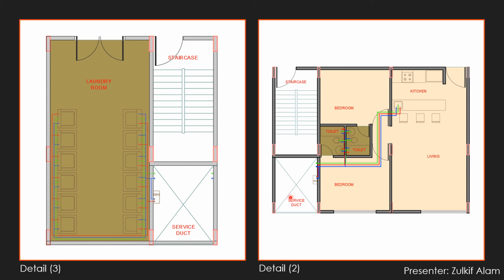Each floor receives a water line through the service duct, which branches off to a water heater specific to each apartment. This water heater provides the hot water system for the apartment. The green line in this diagram depicts the wastewater system, and the red and blue lines depict the hot water and the cold water lines respectively.